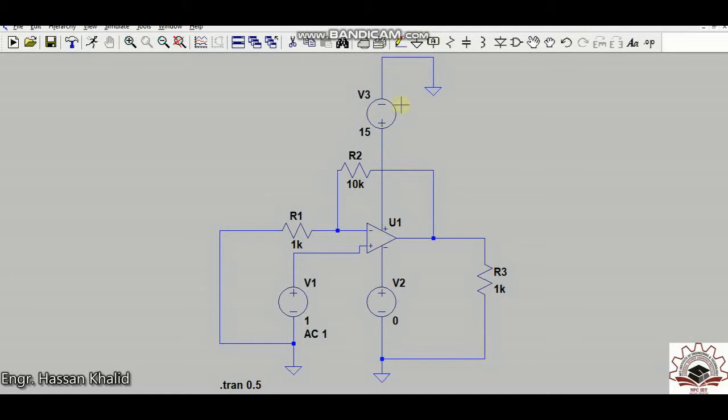Now you need to remind yourself of the basic structure of the amplification circuit from lab number 1, where I was using DC voltage divider biasing, which was biasing the collector side of the NPN transistor. I was biasing the collector with 20 volt in that circuit. Now in this circuit I am just giving 15 volt for the biasing. If you remember that circuit, it is being placed inside this amplifier U1.